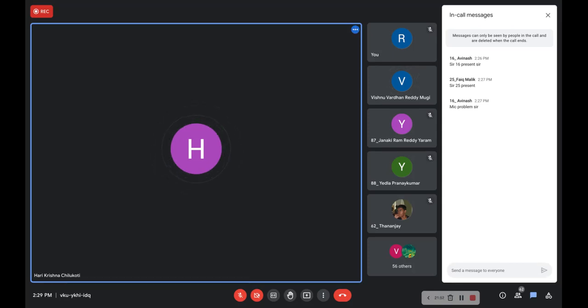That's one point. And the other possible way to control the thermal conductivity of a material without changing its composition is by having grain boundaries. By having the grain boundaries in the material, here we are only ensuring that molecularly we are tuning the boundaries, but the chemical composition of the material does not change. Okay, by having such grain boundaries, we can control the thermal conductivity.